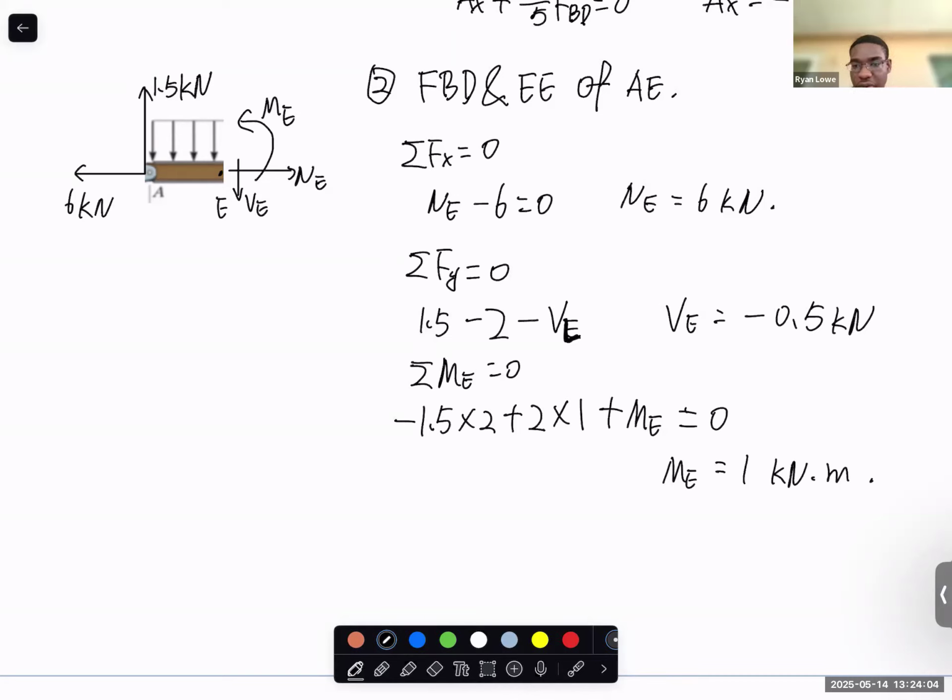This is the different sign convention for internal force. And when we actually do the equilibrium equation for this AE section, now this becomes the external applied force and everything should follow the coordinates. So if it's downward, you should add a negative sign. Counterclockwise, positive. X direction, positive.